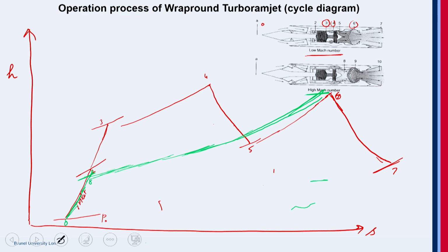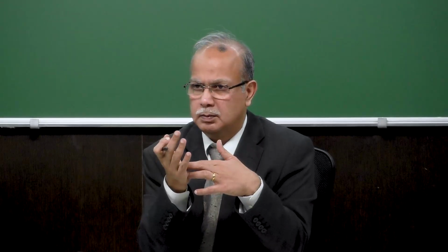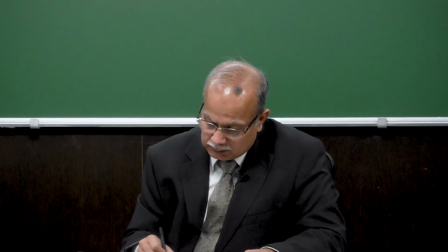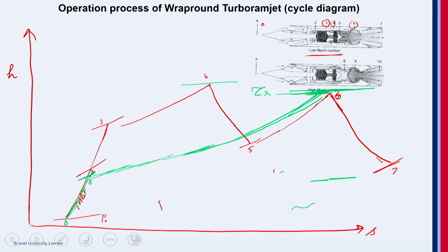The important thing here is that they participate in the same combustor. If it is a different combustor, as in the over-under layout, which means the thermal barrier coating material could be different. But here it is the same. So likely the peak thermal limit here, the thermal limit tau lambda, could be the same. And then it expands here.